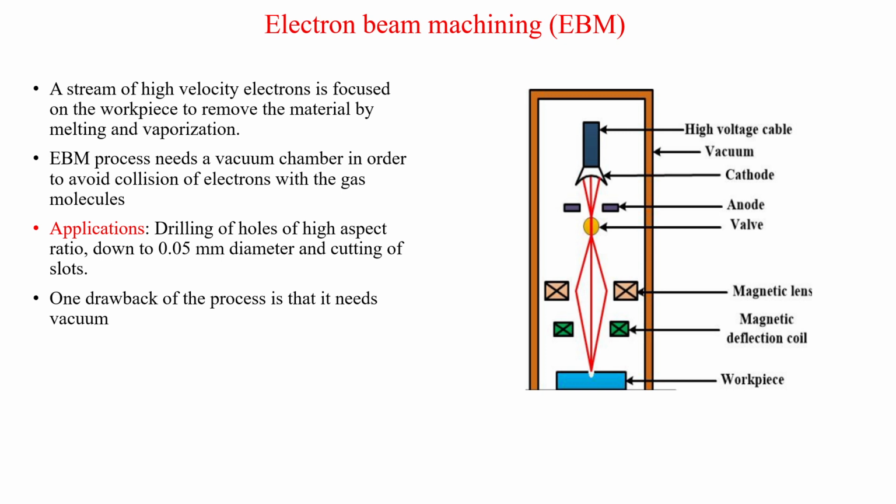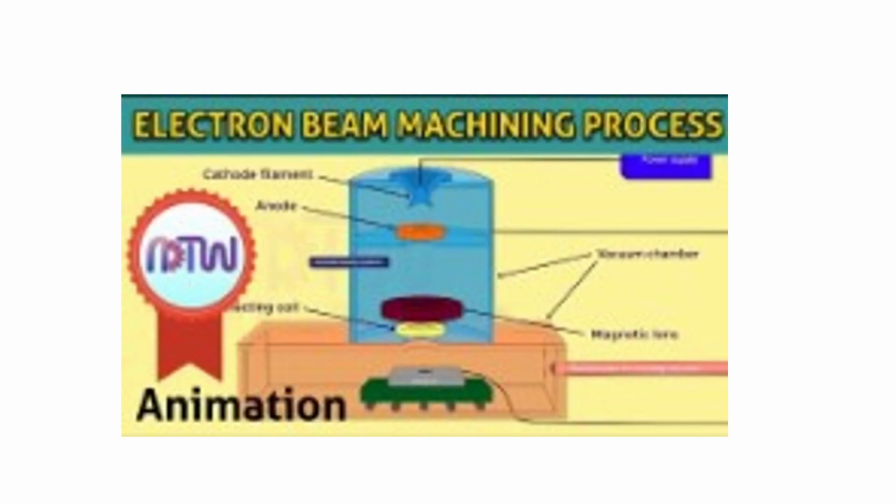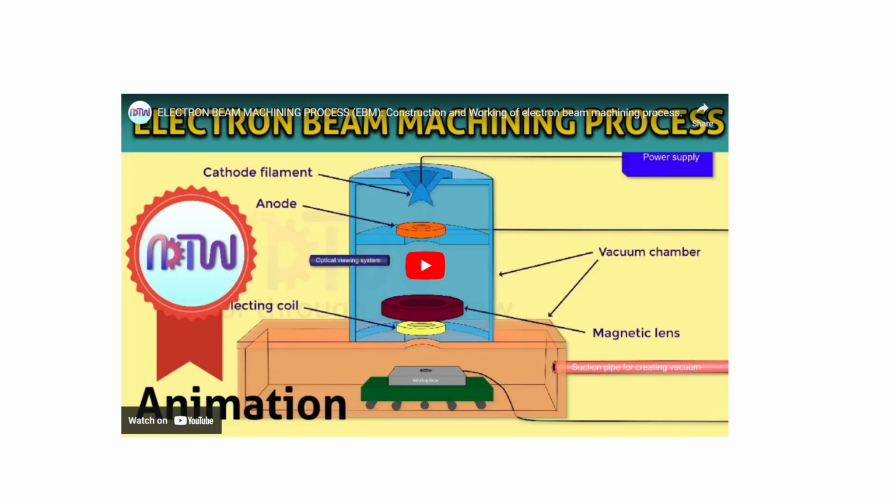Various applications include drilling of holes of high aspect ratio. For very fine machining and drilling, EBM is used. But it is a very costly process because it requires a vacuum and a very high setup. So it is a very costly process. Okay, we'll see a small video on how EBM is done.